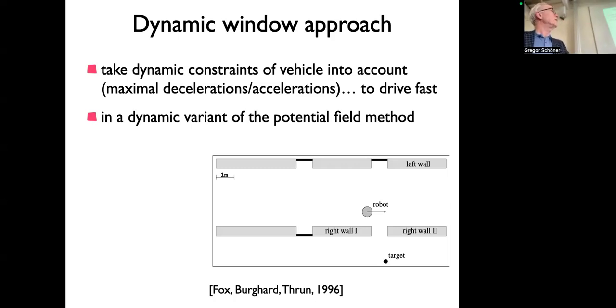So this is also an approach that is still inside some of the algorithms, maybe tuned to other things, called the dynamic windows approach, which is essentially a dynamic variant of the potential field approach. It's actually interesting with respect to this comparison, dynamics and potential field, because it goes to the velocity level. It does it in somewhat odd ways. So the analogy is not totally direct, but there is some analogy. The goal of this was to make these robots move a little swiftly, fast. And that's why it was fun. They made a video. Often you have one cool video and everyone loves that.